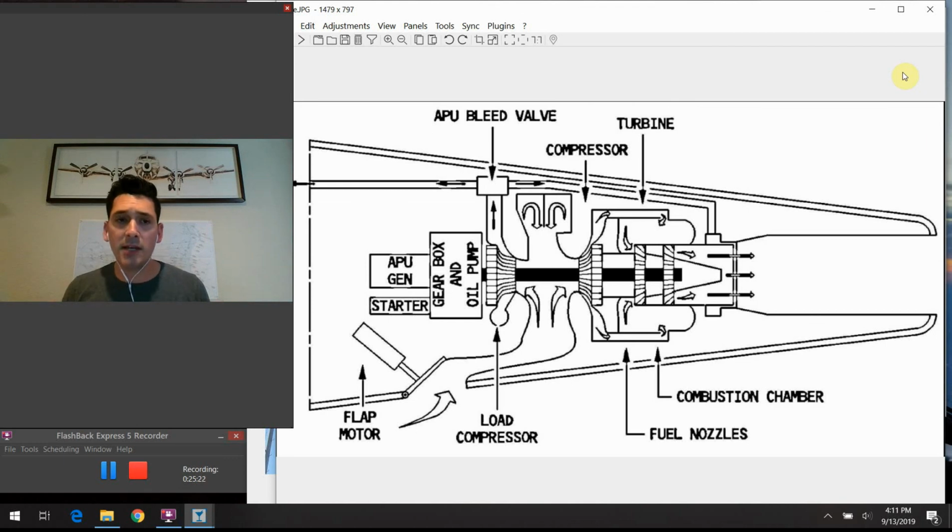So the plane actually starts to heat up in the back. When you start the engines, you have to pull the preconditioned air off as part of the normal procedure, and then you have to use high pressure air to start the engines. It's not until after you get the engine started that you can get bleed air from those systems to bring the AC back on. So imagine what's going on during this whole situation.